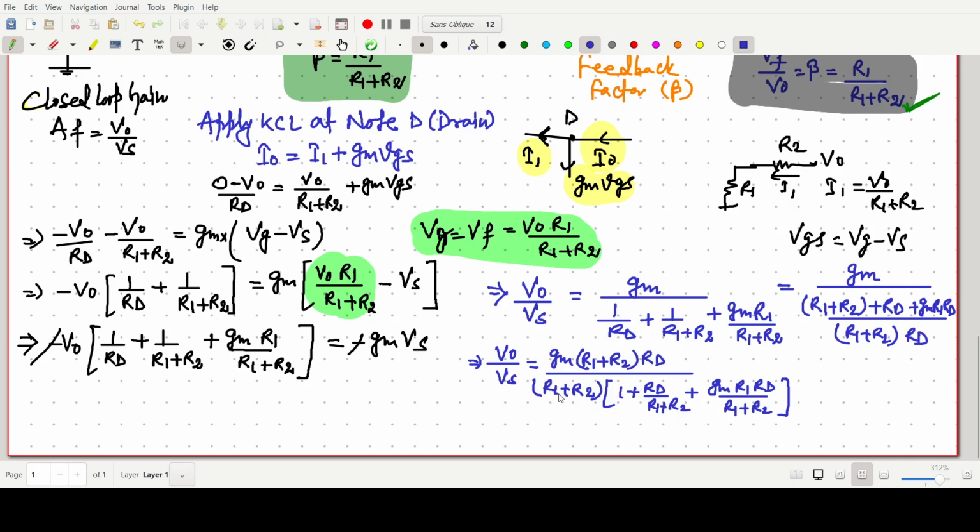Okay, so now this and this will be cancelled out, so this value will be Gm Rd. Okay, and one more relationship there, R1 plus R2 is much greater than Rd. Okay, so this value will be very high. Okay, this expression is given. So this value is very high compared to this one, so this value is nearly equal to 0.